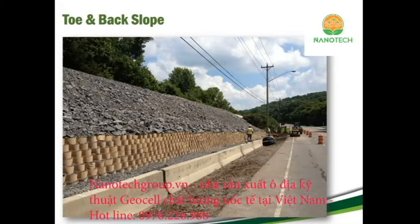For example, there's a tendency to use steep slopes at the top and bottom so as to minimize the height of the wall itself. Slopes steeper than 3:1 are often problematic due to instability and erosion. Therefore, steep slopes within walls should be used carefully, and additional design and details are going to be required.